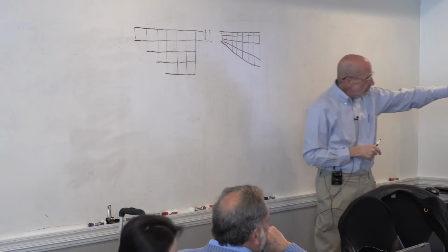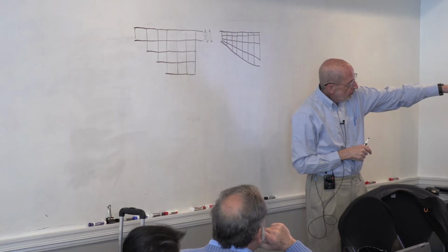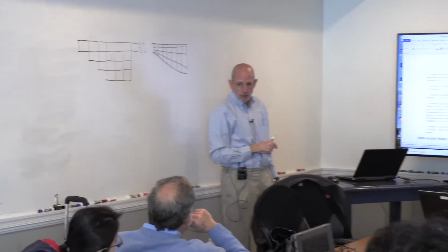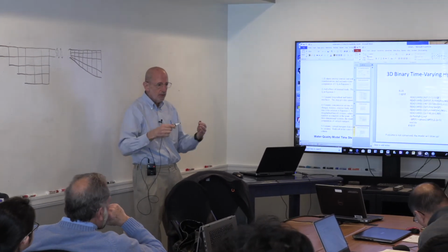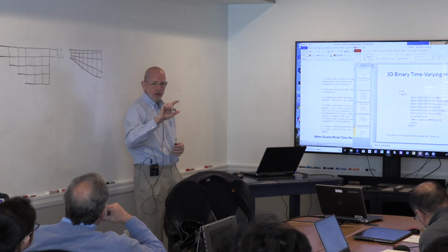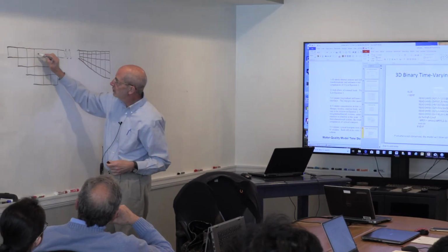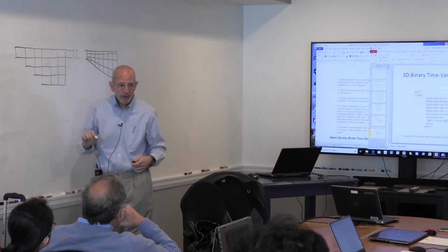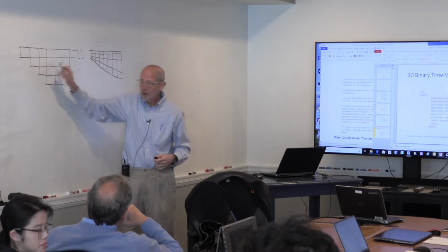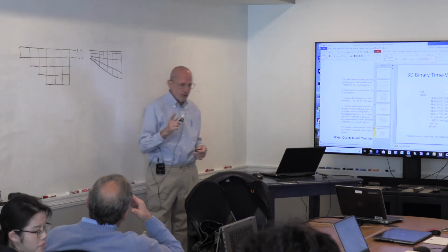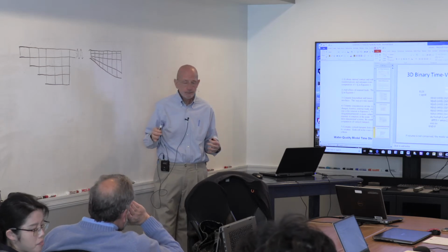So that's why if you look at the first line up there, read height area 1 through number of surface flow faces, NSQF. Every time you read in new hydrodynamics, you have to read in the cross-sectional area of these faces, because as the tide goes up and down, those faces change. But you read these other cross-sectional areas in once when you initiate the model. Once is enough, because they'll never change again.